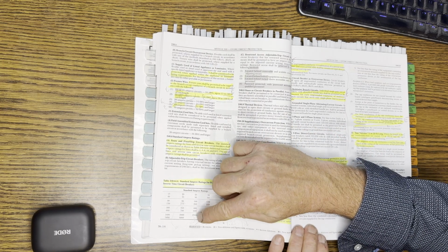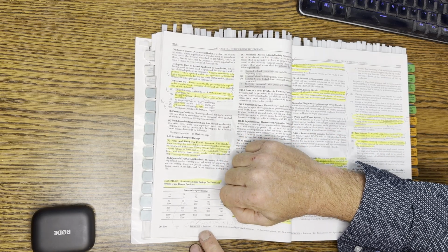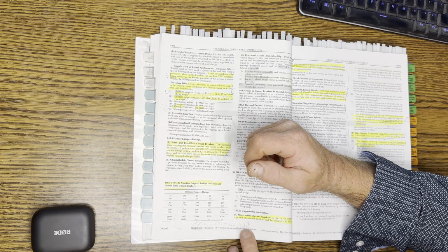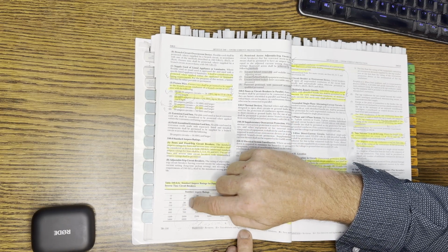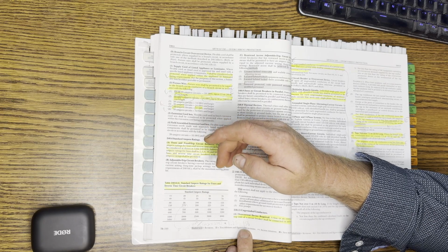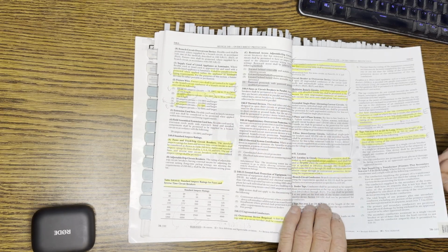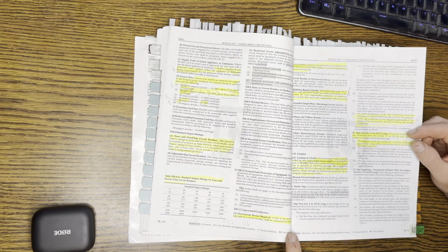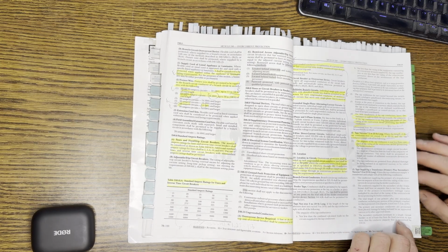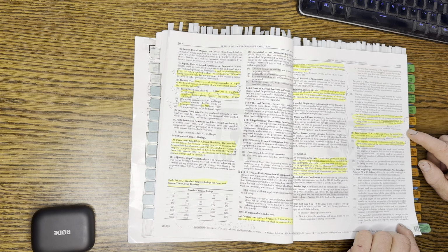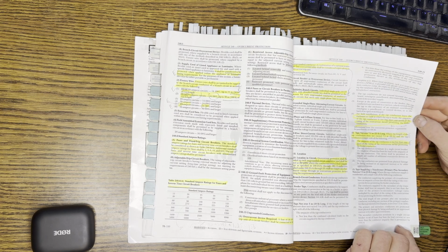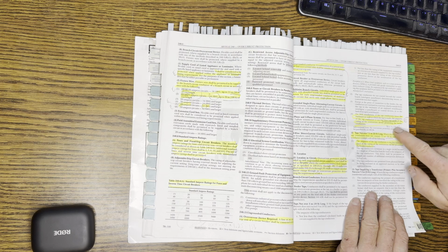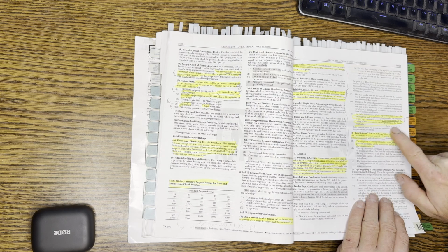Another example, 45 kilovolt amp divided by 1.73 times 208 times 1.25 equals 156. This was an actual test question in terms of calculating fuses, inverse time circuit breakers. So when I have things like that represented in this video, you might want to take a little bit more time to understand that. The answer from the text, from the actual questions on the test, was 40 amps here.